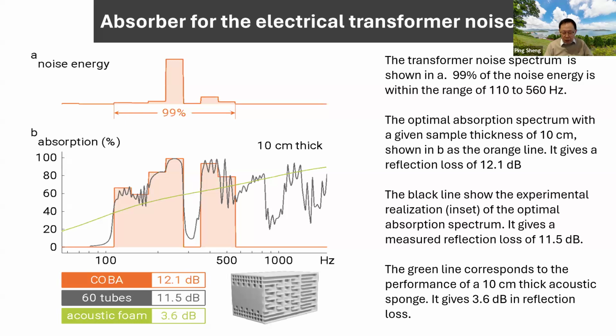Okay, so this is something to illustrate the uniqueness of the metamaterial absorber and the success of something that we can use as a Lego piece. And you can ask, what are the black lines beyond the idealized case? That's due to the higher order resonances in the Fabry-Perot. So they may be unwanted, but they don't hurt. Okay, they don't hurt in the present case, so we don't have to deal with that.